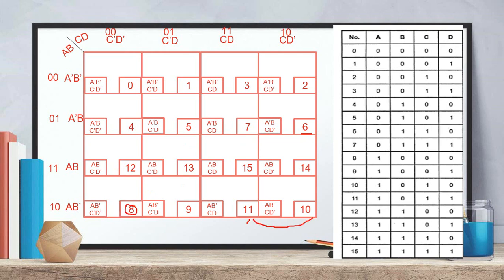So in this portion it is opposite. Again here, start from the last one, 12, 13. After that 14 and 15. So you have to remember very importantly how the KMAP is formed. It is not the similar way of 0, 1, 2, 3, 4, 5, not like that. It is something like 0, 1, 3, 2. If you already know about gray code, it is similar to the gray code options. So we can move on to how to represent from the truth table to here.